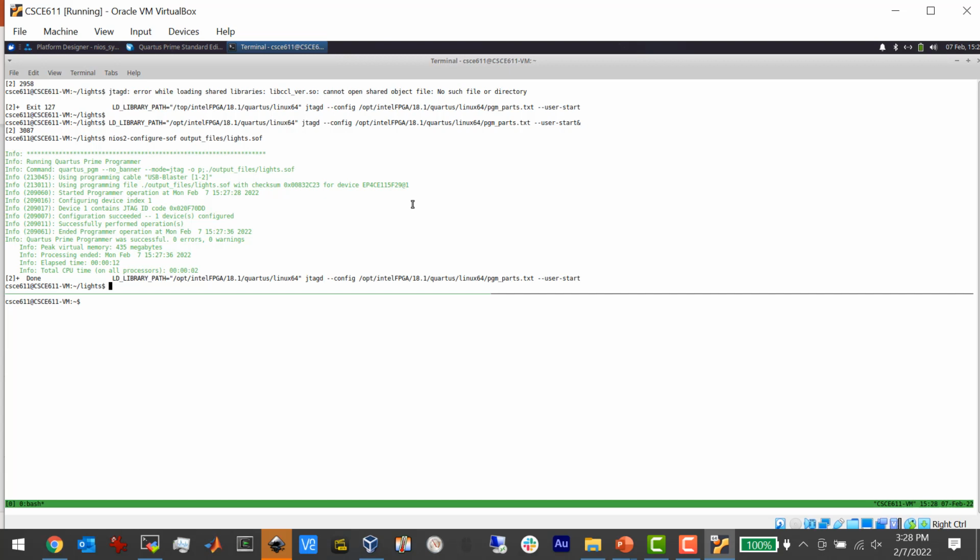So if your goal is to actually light these up and you see them dim like that, your connections are dead. There's something wrong, they're not connected. But I didn't actually connect them to anything in the FPGA design, which is why they're dead. It's also why the hex display went off.